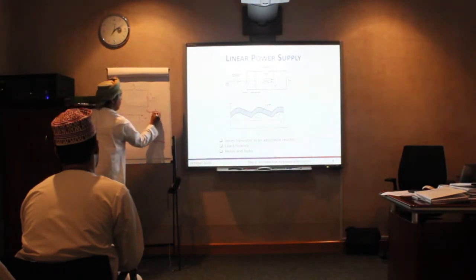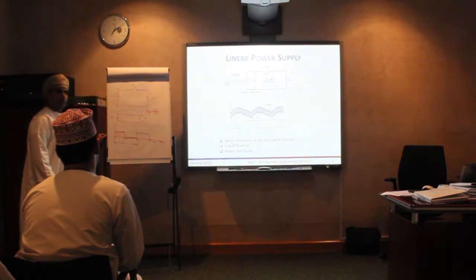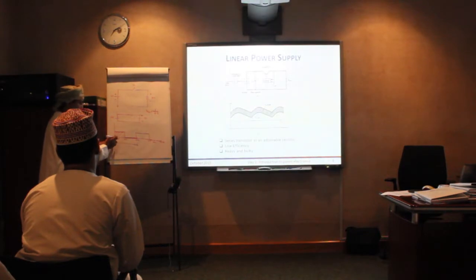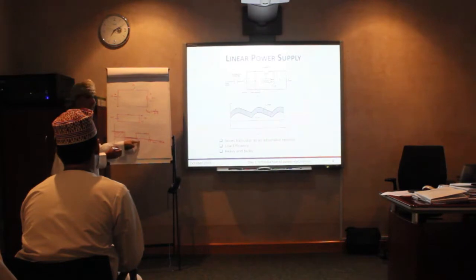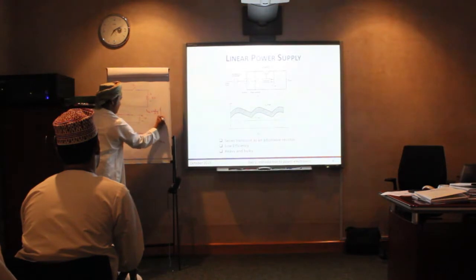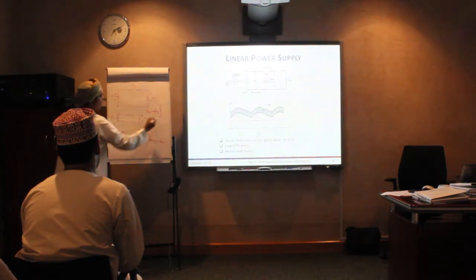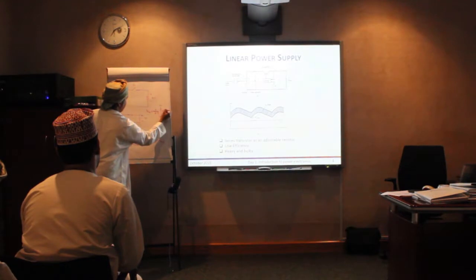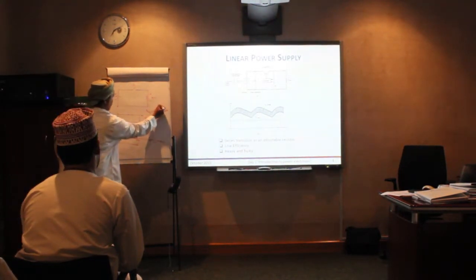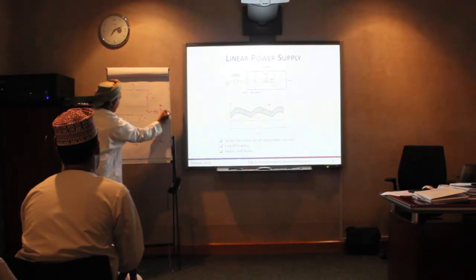The period is 0.2, right? And the area under that period from 0 to 0.2, but from 0 to 0.1 there is 10 volt, and after that 0. So the integration is only from 0 to 0.1 of 10 volt dt. Sorry for the typo.